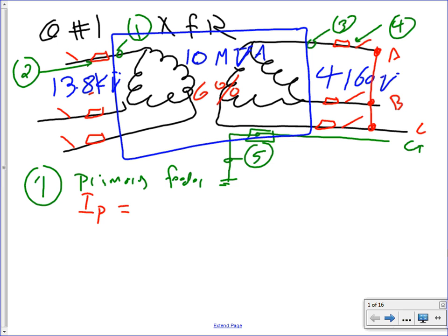They always use 3-phase. For example, North Star Steel has equipment where they tie the motors directly to 4160. There's a lot of equipment that works at 4160. So the neutral is not needed. In a case like this, because the neutral is not needed, the only thing you need to provide here is a grounding electrode system.